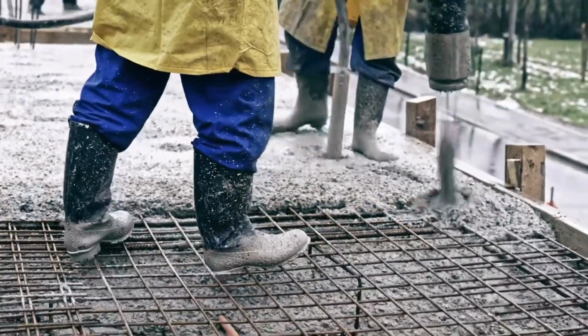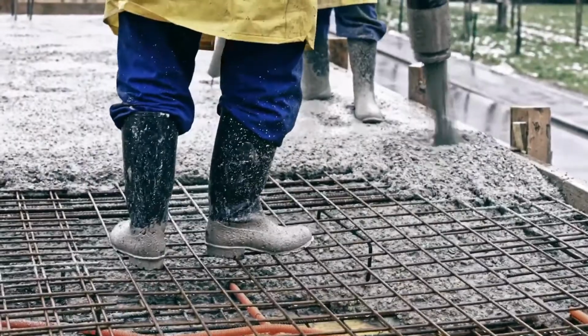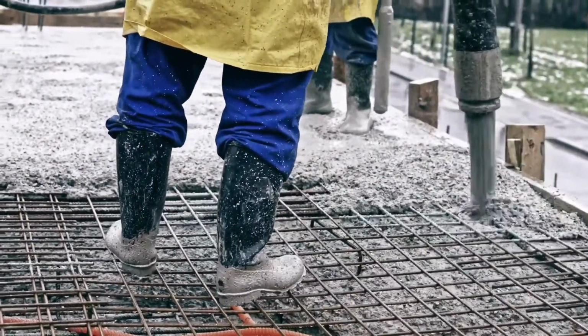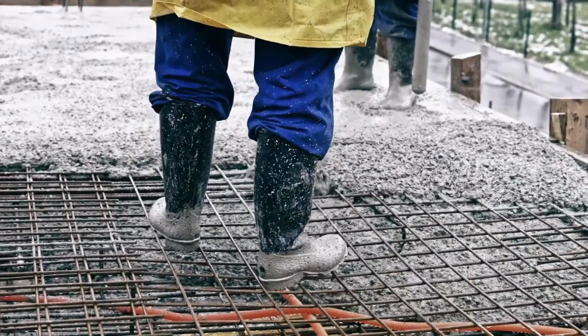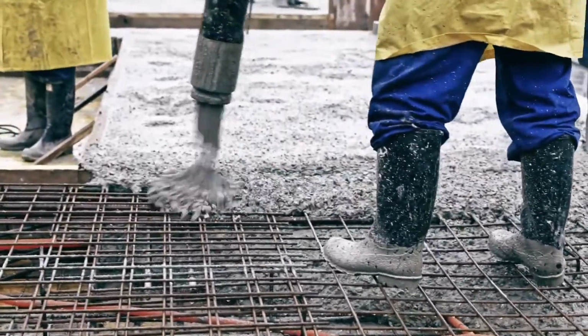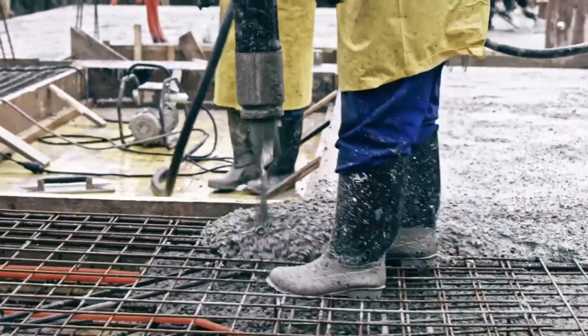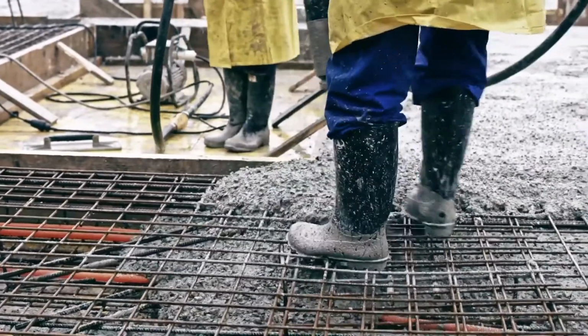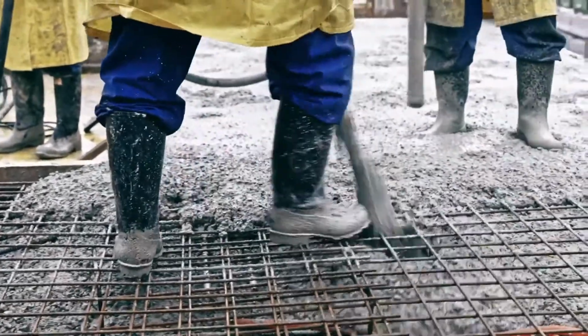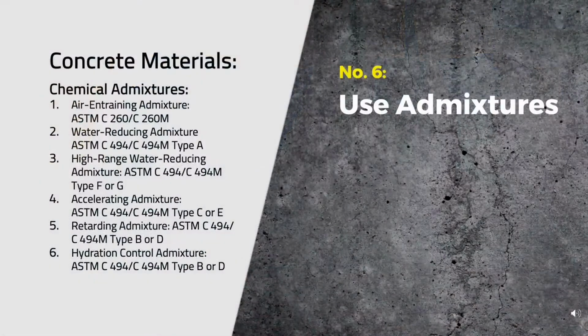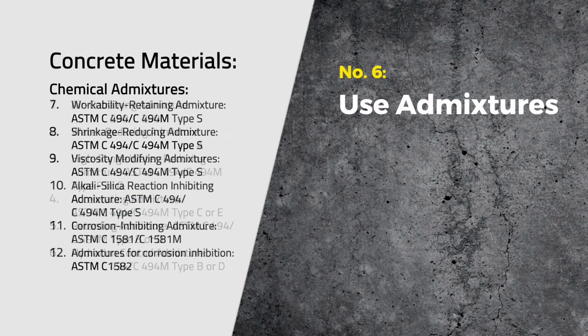As an example of how effective admixtures can be, using a water-reducing admixture that reduces water content in a mixture by 12% will result in a reduction of cement content by 70 pounds for equivalent slump and strength, and in a carbon reduction of roughly 10% for 4,000 psi concrete. Here is another simple solution. All admixtures that meet an ASTM standard should be permitted and listed in your concrete specification, and those that do not meet a standard should still be considered with proper submittals and technical backup.